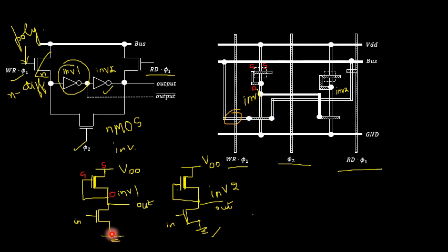So this is done. The output of the NMOS inverter should get connected with the input of inverter 2. So my inverter 2 is appearing over here, again a replica of this, just copy paste once again. So this is your NMOS inverter. Pull up is the depletion type of NMOSFET. Pull down is the enhancement type of NMOSFET.